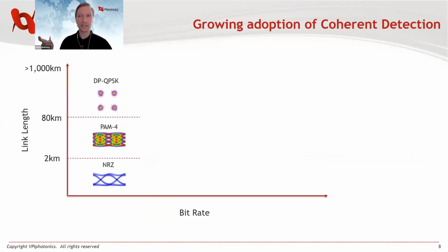Currently, coherent detection is the mainstream choice for long-haul networks, mainly because it's more tolerant towards optical impairments, such as chromatic dispersion. Direct detect techniques are used at shorter link distances, for example inside of the data center. Techniques like PAM4 and NRZ are a lower cost option for these shorter links because they don't require the complex DSP ASIC, but they do have their own data rate limitations.